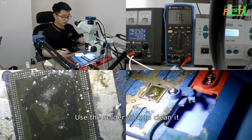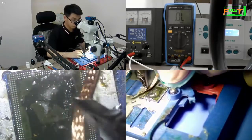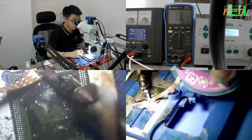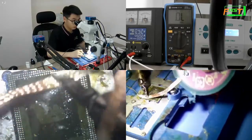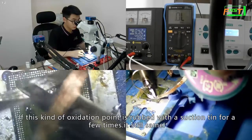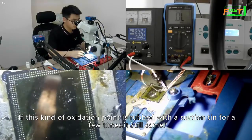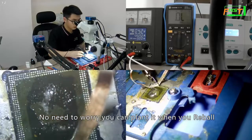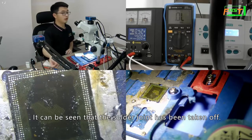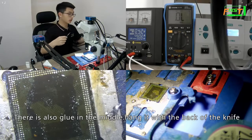Use the solder wick to clean it. If this kind of oxidation point is rubbed with the solder wick a few times, it's still the same. No need to worry, you can plane it when you reball. It can be seen that the solder joint has been taken off. There is also glue in the middle, to be scraped with the back of the knife.